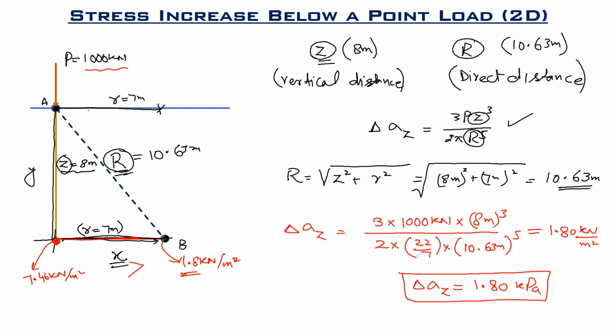So basically we follow a pressure bulb. We have seen this type of pressure bulb in soil mechanics. The stress increases to a maximum value and then starts decreasing. On the horizontal sides the same trend is observed. The maximum stress due to this point load will be exactly below the point. Say we want to determine the stress at 4 meter depth, so we will have maximum stress at 4 meters exactly below the point.